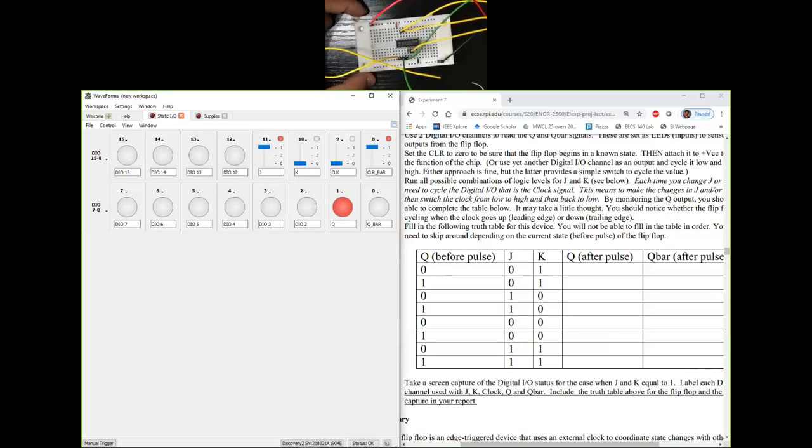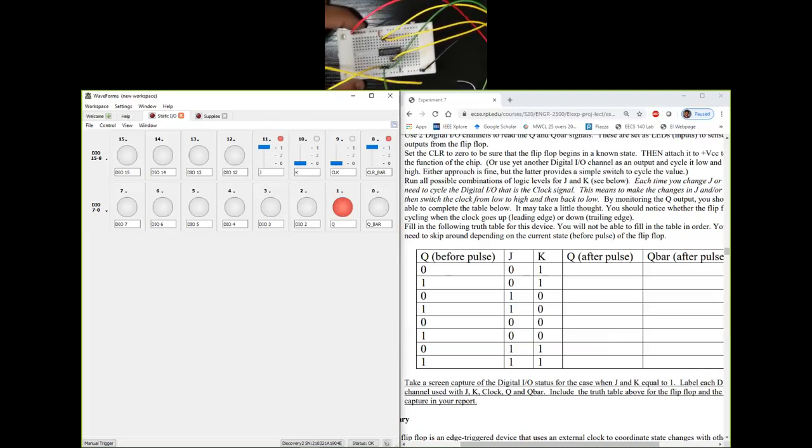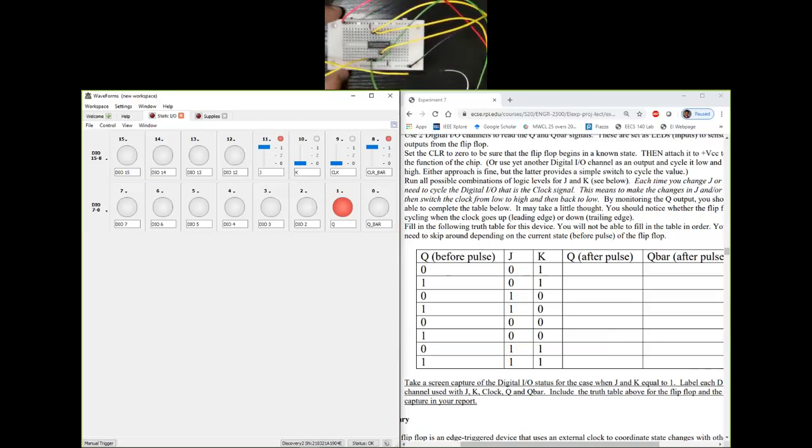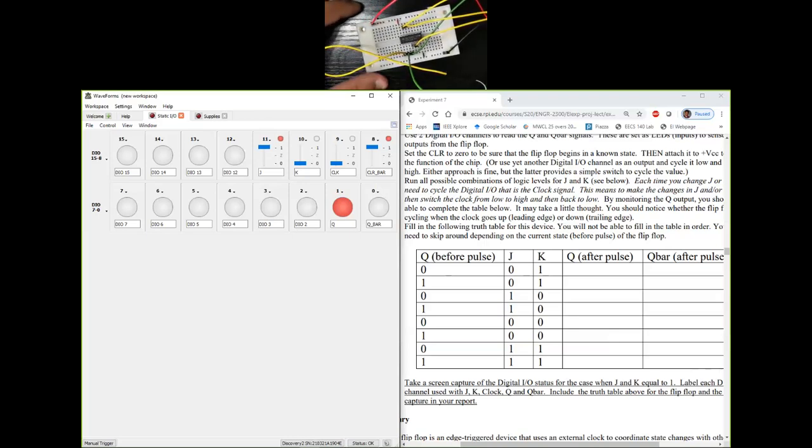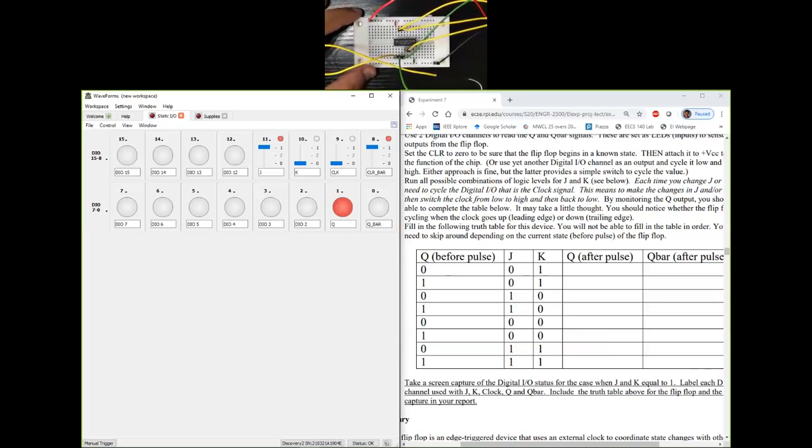So it's not going to respond to a sine wave the same way it responds to a square wave. It is probably going to select some voltage input to be a low, and there is going to be a lot of time where it is going to be in the undefined region of the voltage input. So it's not going to give you a reliable behavior.